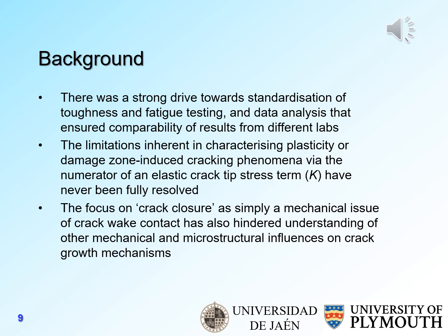And the focus on crack closure as simply a mechanical issue of crack wake contact, in my view, has also hindered understanding of the other mechanical and microstructural influences on crack growth mechanisms, and hence has limited our understanding of crack physics.